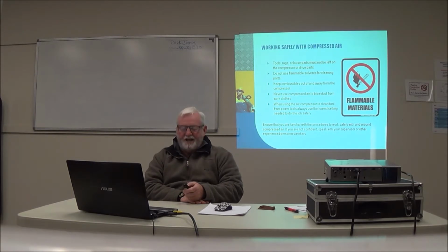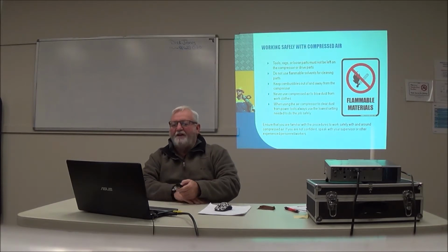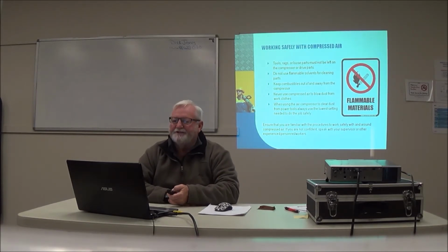Do not use any flammable solvents for cleaning parts. Keep combustibles out of and away from the compressor. Never use compressed air to blow dust from work clothes. When using the air compressor to clear dust from power tools, always use the lowest setting needed to do the job safely. Ensure you are familiar with the procedures to work safely with and around compressed air. If you are not confident, speak with your supervisor or other experienced personnel or workers.